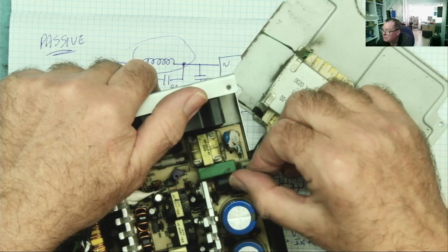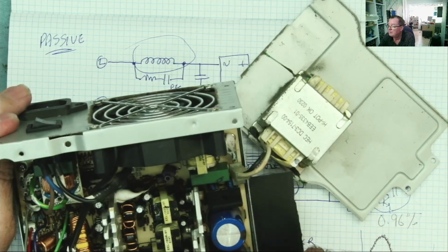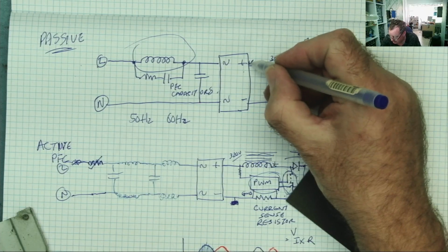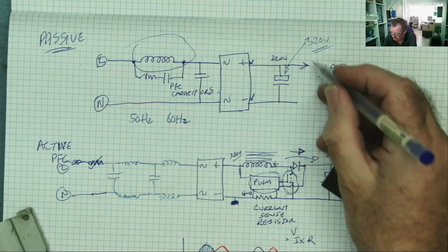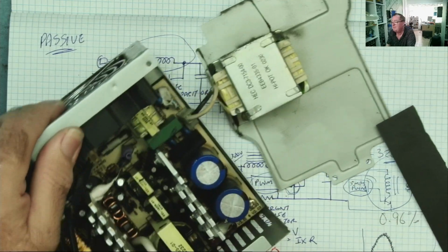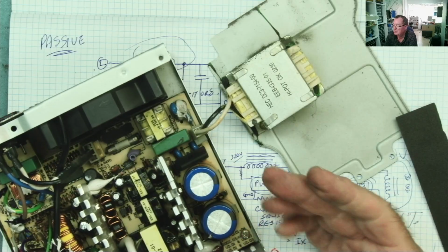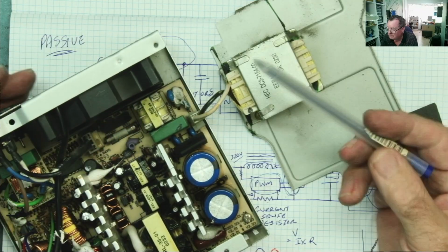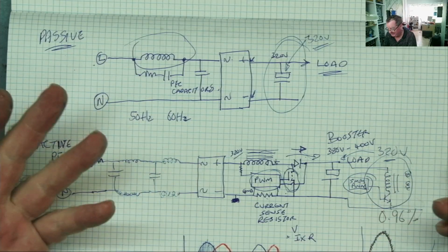But you can be quite smart, because what you have here is the bridge rectifier, and we can see the legs of that one. So we can measure across here and here with our multimeter and see whether or not there's any charge in this capacitor before we start to dismantle the thing. And if you don't touch it with your fingers, touch it with the metal chassis, and that'll make a big flash and a bang, and you might not be electrocuted, but you probably need a new pair of trousers, okay? So that's what we would do. We would check across the bridge rectifier, because in many cases we can get to it.